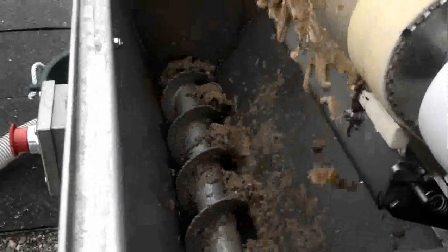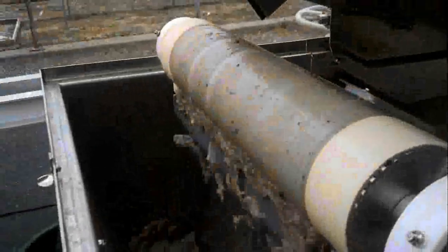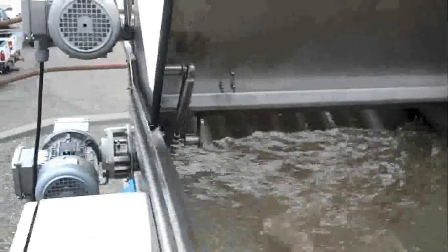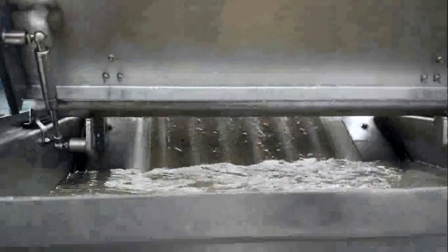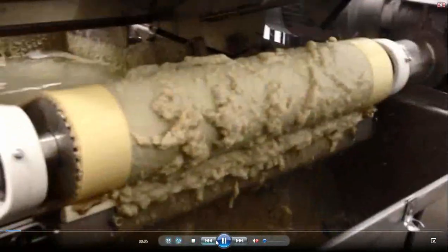The operations are very similar when we're talking about combined sewer overflows. The key difference would be your influent water is going to be probably half the strength or less with combined sewer systems and relative solids. And we're going to go with a tighter micron sieve on that mesh so that we get higher capture rates. This next video I have included here to demonstrate how capable this system is at taking very high slugs of solids, or slugs of very high solids concentration.